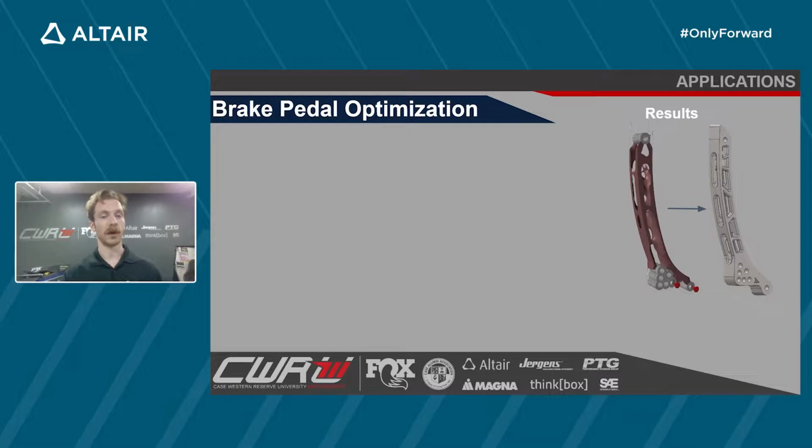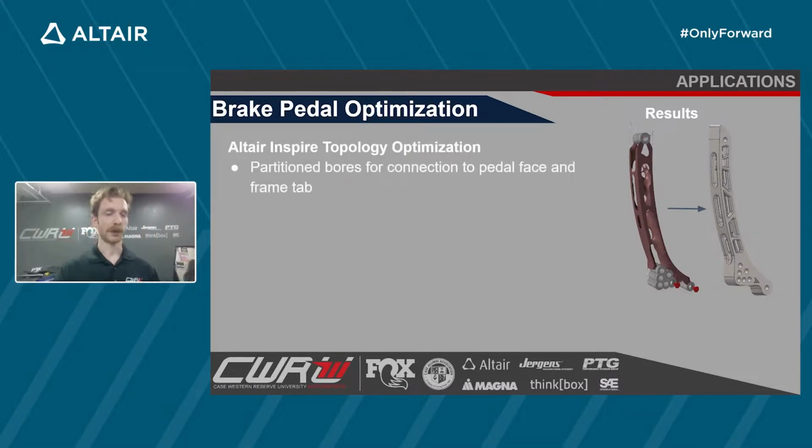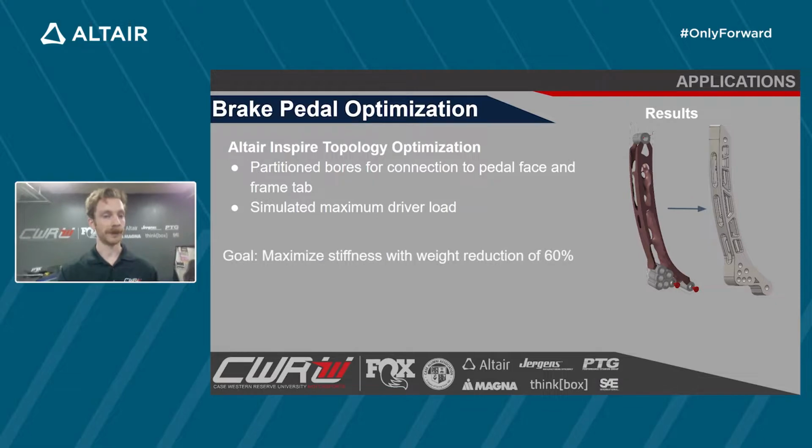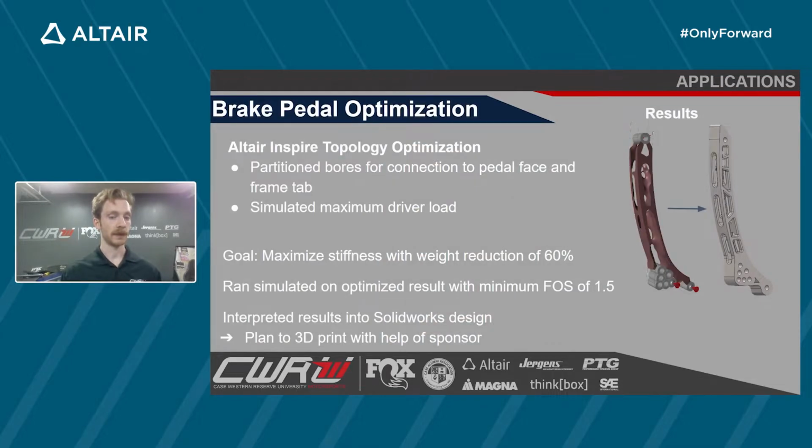So we took our brake pedal into Inspire. We were able to partition our bores to keep that same design intent. We simulated maximum driver load, and we want to maximize stiffness this time. And we got a weight reduction of 60% with a minimum FOS of 1.5.